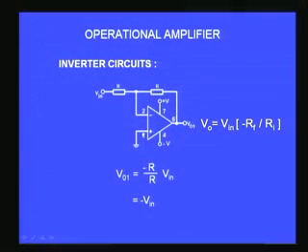So now let us see in more mathematical terms how it is. You can see that the non-inverting input is grounded, this is the first part. We applied the input only at the inverting input, and the gain is R by R, therefore it is 1, but because it is inverting you have a negative sign. Minus R by R times V in is the output voltage, VO1 I call it, because it is the first configuration, and therefore it becomes minus V in. Or if I want to look at it as the gain, VO1 by V in is equal to minus 1. You can all see this, very simple.